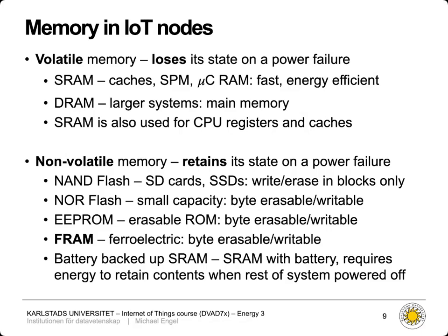And finally, there's another way to achieve non-volatile memory. And this makes use of the fact that SRAM doesn't need refresh, so you don't need to run refresh cycles all the time, and that is relatively low on energy consumption. So this means you can actually attach a backup battery to an SRAM chip and then preserve the contents of the SRAM as long as no other energy is available. This is very often done for very small SRAMs, for example, in chips that also include a timer for keeping real-time information, and then this also contains information about additional current data, like the current date or additional configuration data you need in the system. So usually SRAM batteries only last for a relatively short amount of time, but this can still be like a year or more. But these are also relatively expensive.